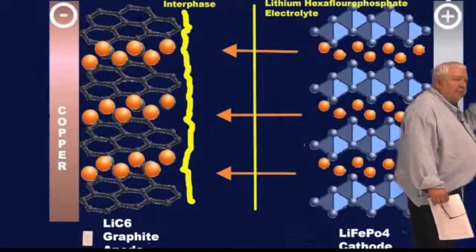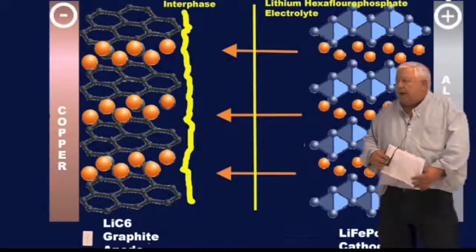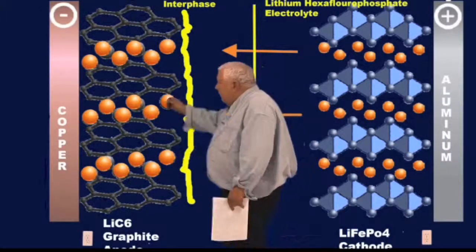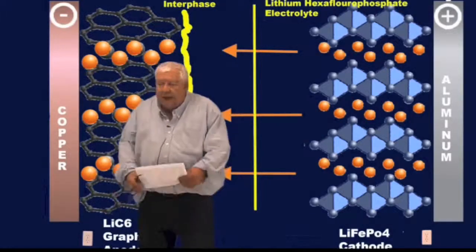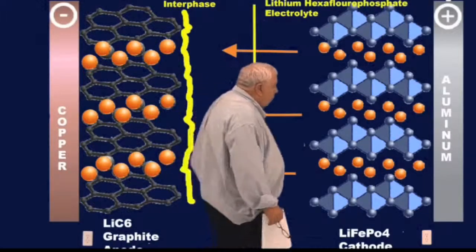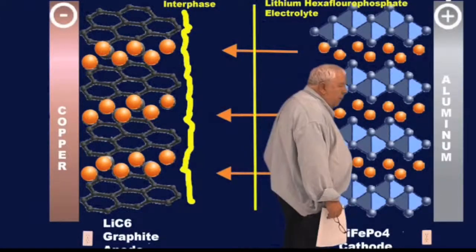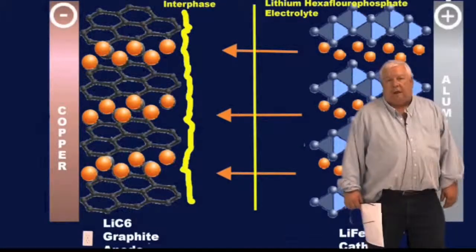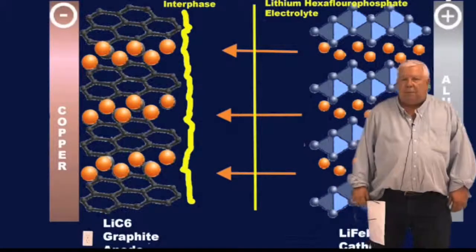Once that oxygen starts to come out, now we're feeding the whole thing. The oxygen starts to react with the electrolytes, with the rest of it, and the result can be an extremely hot fire, and we've seen the results of cars burning to the ground, primarily from overcharging. Let's talk about over-discharge and how that's all better, because it can burn your car down too.